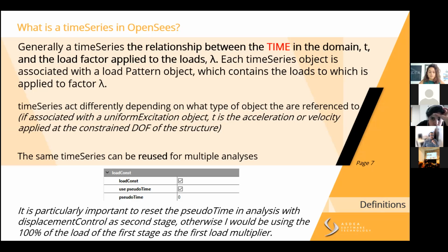So when you are at the end of your analysis command, there is this crucial point where you can decide if you want to keep the load constant in the next stage of your analysis, and if you want to reset the pseudo time of OpenSees to 0 or to another number. If this number is editable, you can decide.